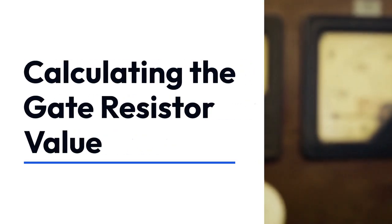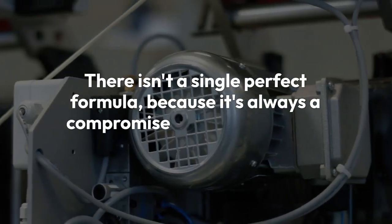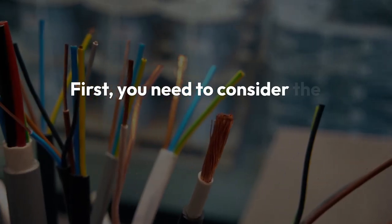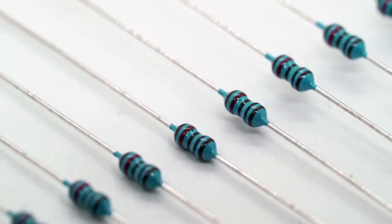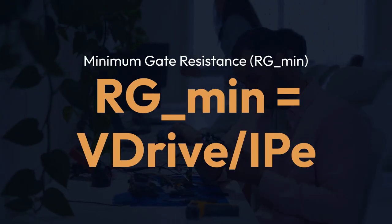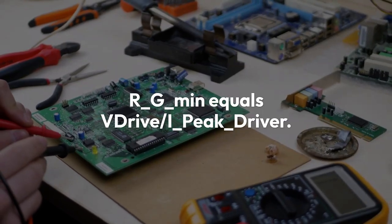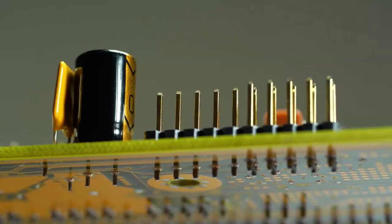Now, let's talk about calculating the gate resistor value. There isn't a single, perfect formula because it's always a compromise between different factors, but we can establish a good starting point. First, you need to consider the maximum peak current your gate driver can supply or sink. You must ensure the gate resistor limits the peak current to a safe level for the driver. A rough minimum gate resistance, R_G_min, can be calculated as the driver supply voltage divided by the driver's maximum peak output current, R_G_min equals V_drive/I_peak_driver. This gives you a baseline. Your chosen resistor should generally be equal to or larger than this value.